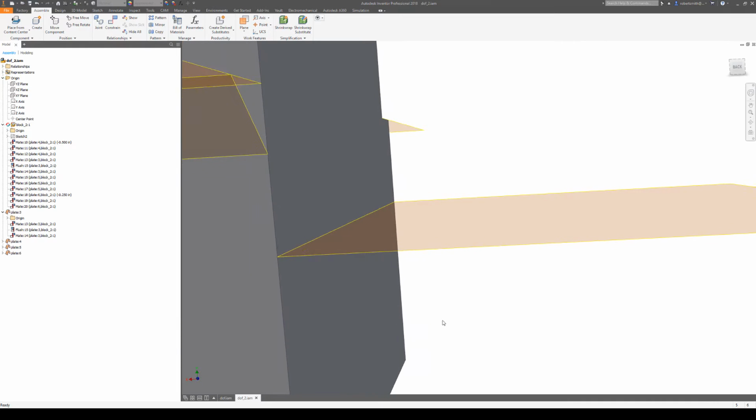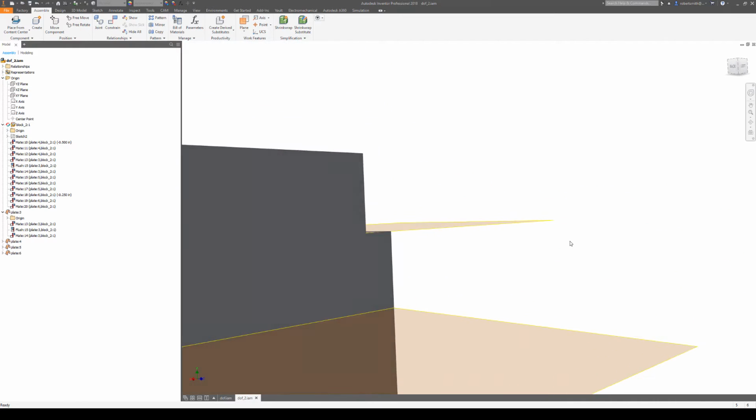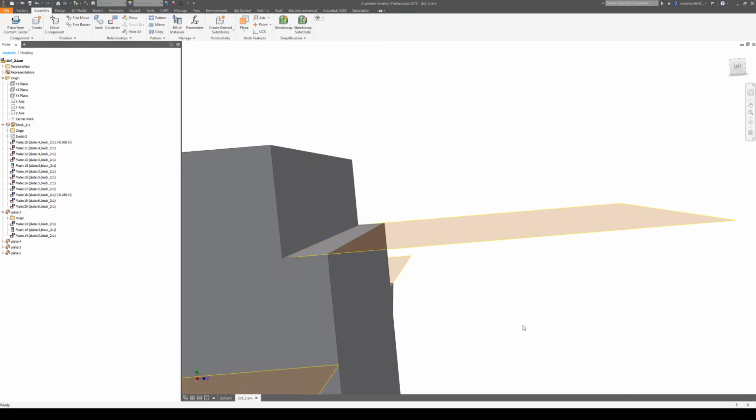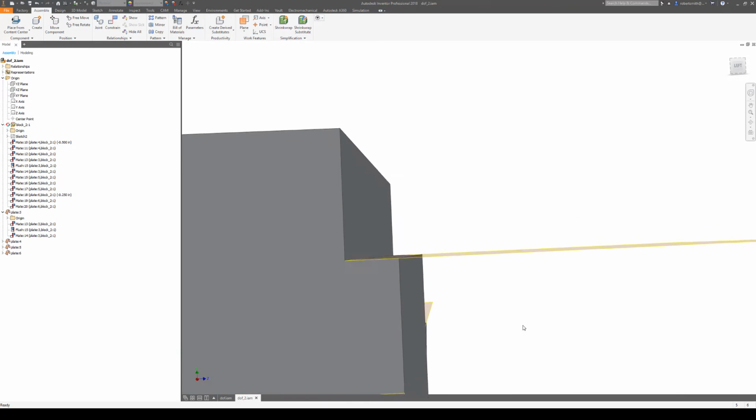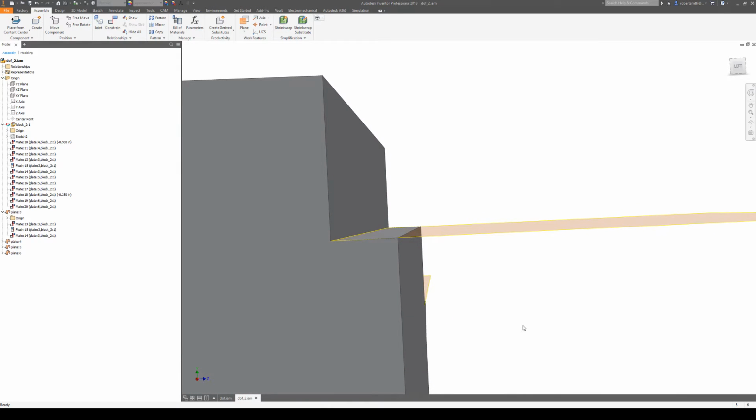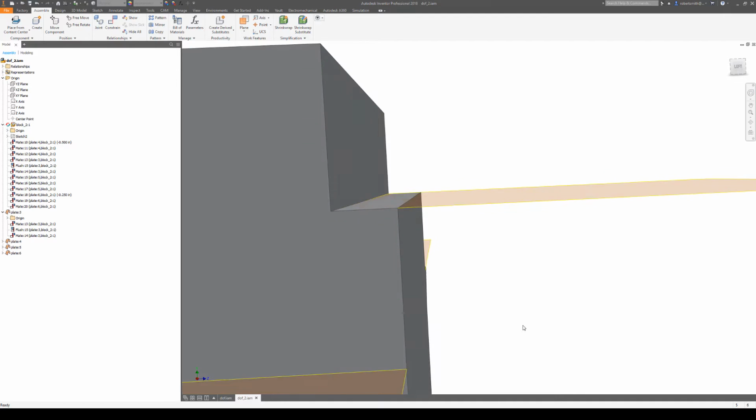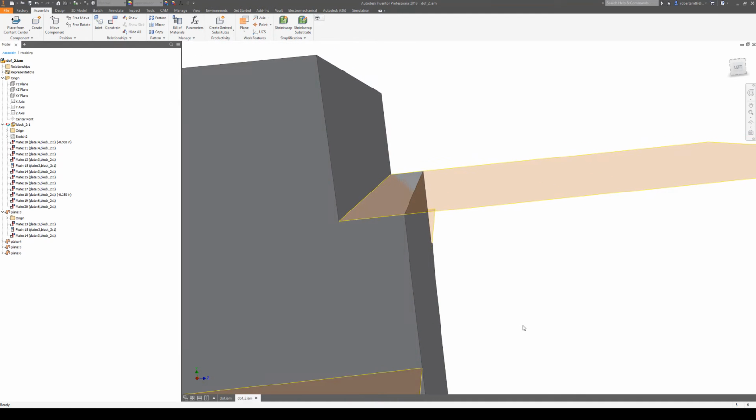So what do you do? Well, I've seen a few techniques employed. One is to just put a step in there. Obviously this one's exaggerated, but just even a little step, enough to get more than one row of nodes where those two things meet. You are modifying the design simply for analytical purposes. It's not something that's physically there in the model. But if you think about it, that tends to be pretty common in FEA anyway.